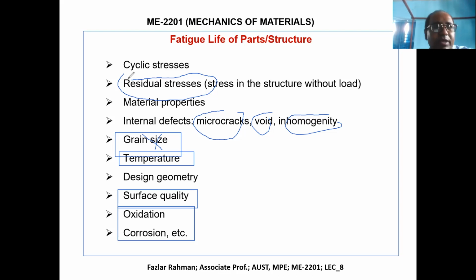For example, you make a gas cylinder. You take an aluminum sheet or steel sheet, bend it, then weld it. But after bending, you need to make sure the material will not try to go back to its previous position. If it tries to go back, that means it will generate some stress inside. So after you bend the sheet, you have to do some heat treatment called annealing.